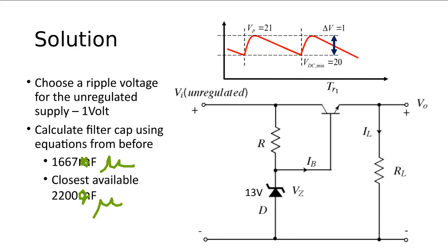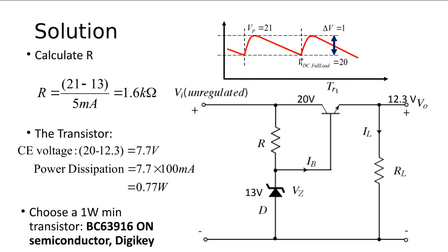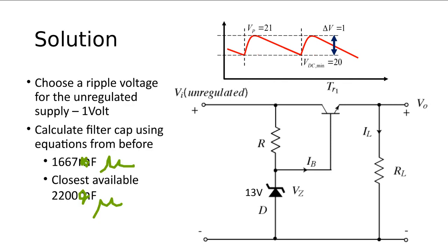So 2200 microfarad, and the working voltage here, seeing that we're working at about 20, we're asking the system to cater for a peak voltage of about 21 volts DC, then I would probably go for a 35 volt capacitor. The next closest one would have been 25 volts, but it's a little small, so I would probably go for 35. Okay, that's the next one up there. You wouldn't get a 30. So you have that.